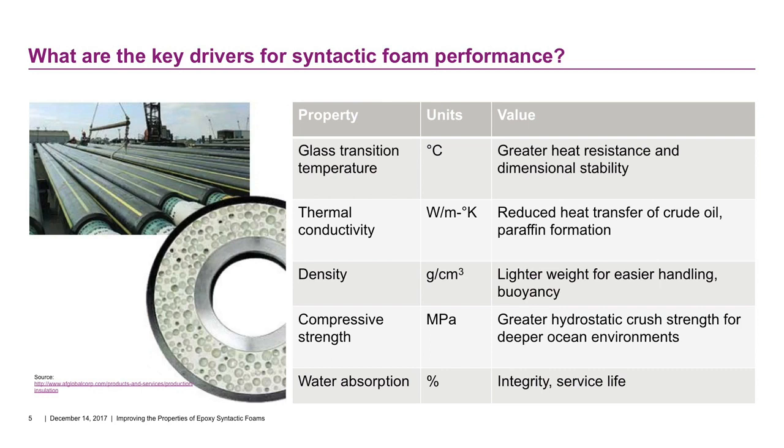And overall water absorption: how well can this composite material resist the ingress of water, either on its own or via crack formation or any type of damage that occurs to the material? How well can it stand up? So this speaks to its integrity and its overall service life.